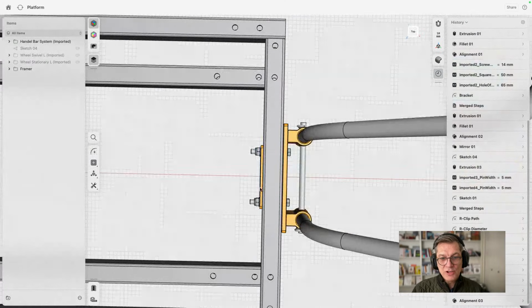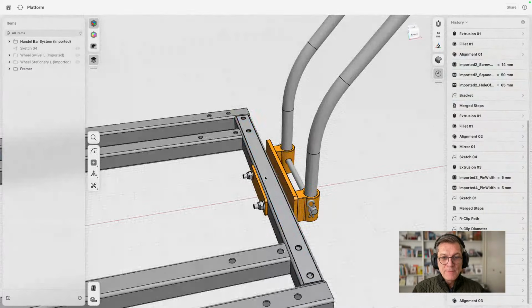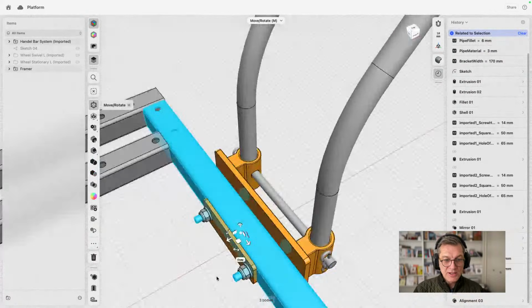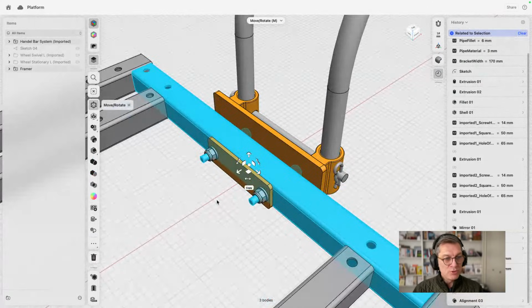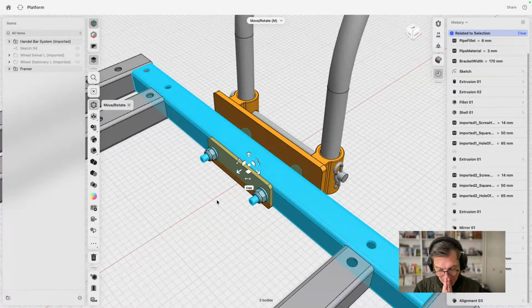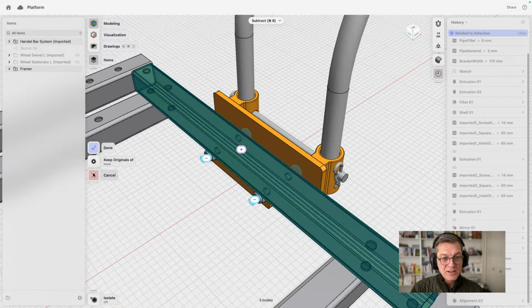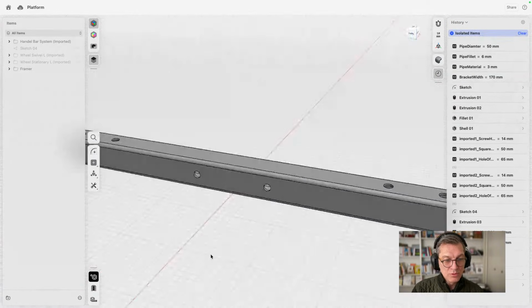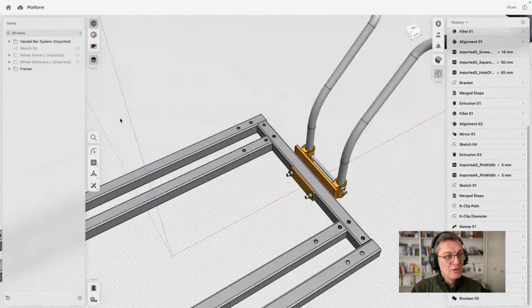I do have the screws here inserted. So as a following step, I could select my square stock, select the pipes, and then use the geometry of these pipe cylinders. They're just representing where a screw would be. And the screws are not custom made, they are mass produced. So we can represent them basically just with a cylinder for the opening and then use them to cut these openings. And then there is the hole. Very good.